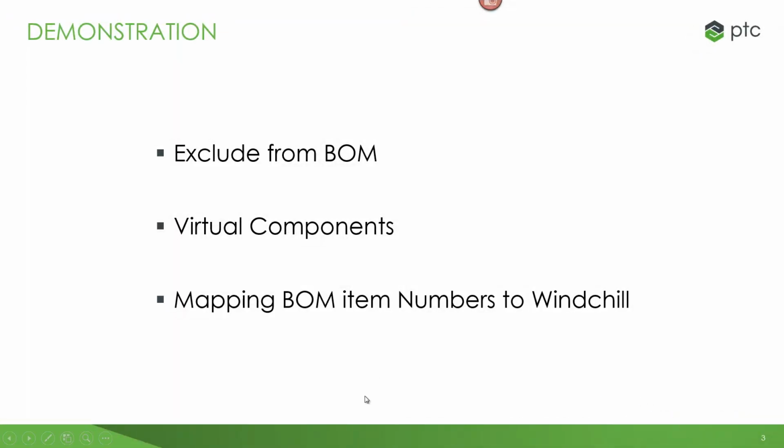In this video we have looked at specific capability regarding BOM management inside Windchill that works with SolidWorks, specifically looking at exclude from BOM marking in SolidWorks, management of virtual components and how they behave, as well as mapping BOM item numbers to Windchill find numbers.